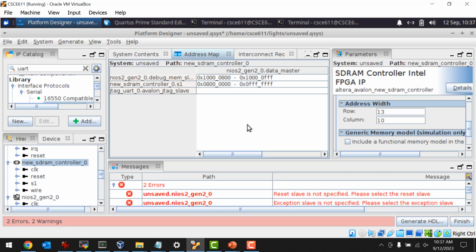Same thing with Arduino. In fact, any processor that doesn't have an operating system is guaranteed to have a physical address mechanism. There's only one version of Linux I've ever seen that uses physical addresses. There's a version of Linux called uClinux, which stands for Microcontroller Linux, and it's the only one that allows you to use physical addresses. However, the Nios processor does have a memory management unit, and you can run virtual addresses on here too. I've just never tried that. I don't know how that works. I mean, you have to run Linux obviously on it for that to make any sense.